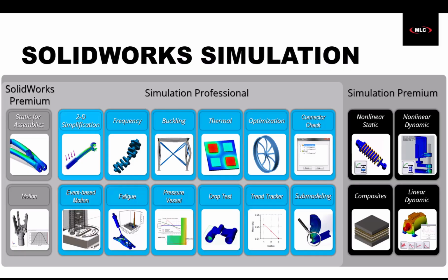We can refine the mesh, do whatever we need to do, but it's going to take all of the displacement inputs on the edges of this cut material from the large assembly and apply them to the submodel. So we still get accurate deflections, but now since we have a much finer mesh, we can get much more accurate stress results without having to wait hours or days sometimes to get an accurate stress.